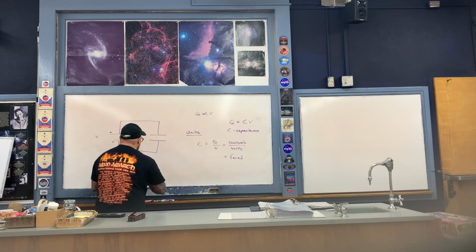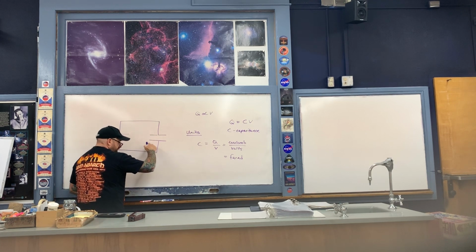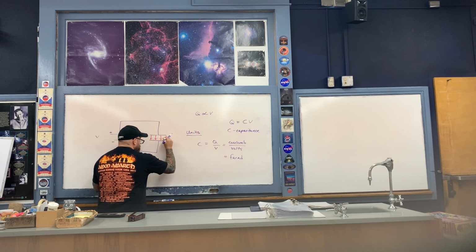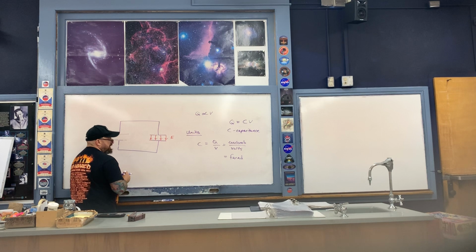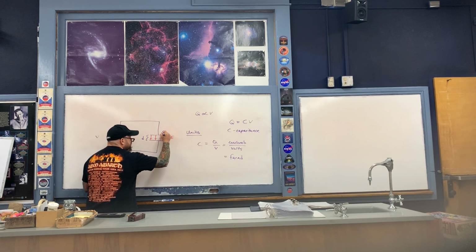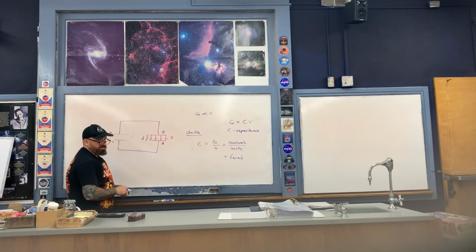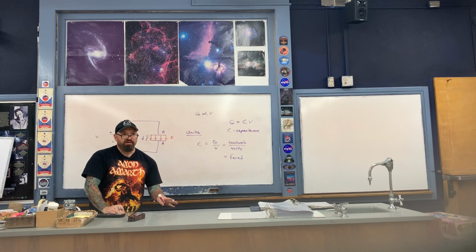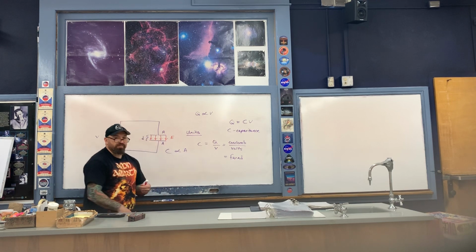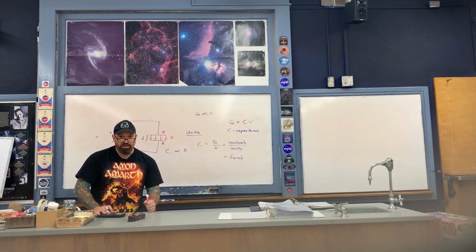Okay, now on this same diagram, this right here was the positive side and this was the negative side. So once the capacitor is charged up, as we say, there is an electric field that is present. The two plates here are separated by a distance d, and the plates themselves have an area A associated with them. The bigger the area, it's like the bigger your gas tank, the greater the capacitance. In other words, the more charge, and therefore the greater amount of potential energy that can be stored. In other words, capacitance is proportional to area.